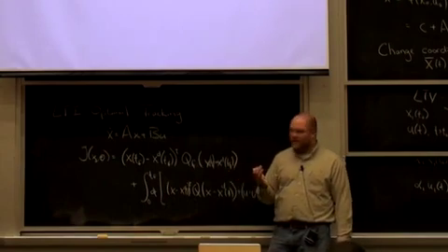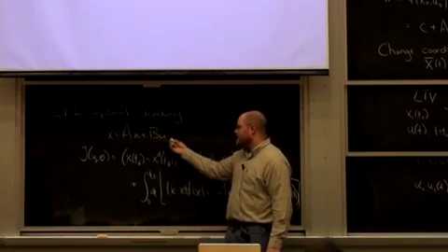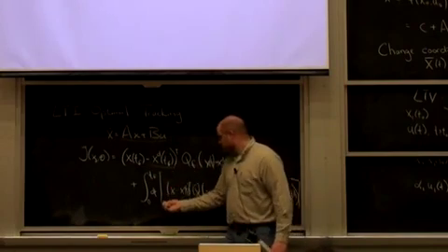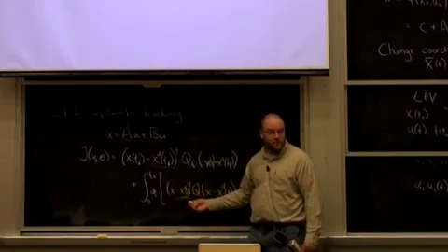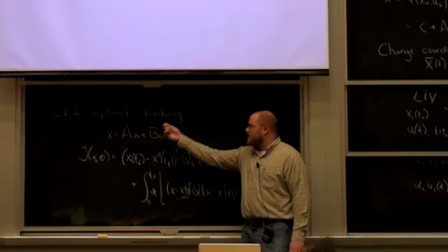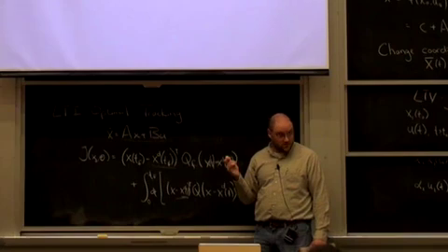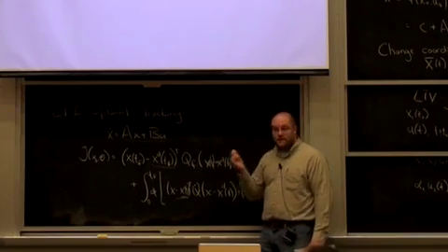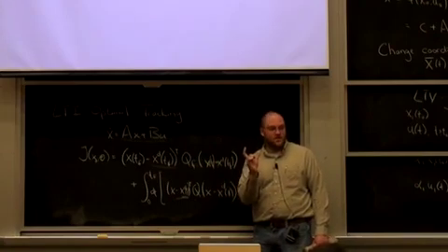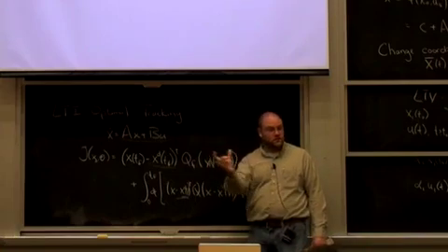Now it's actually still an LTI system, but my cost function is time varying because I have this desired trajectory that varies with time. The result, I won't write it down again. I can do this Riccati equation back up, right? The only difference is that the quadratic bowl is no longer going to be centered on the origin. The quadratic bowl is going to move with that desired trajectory.